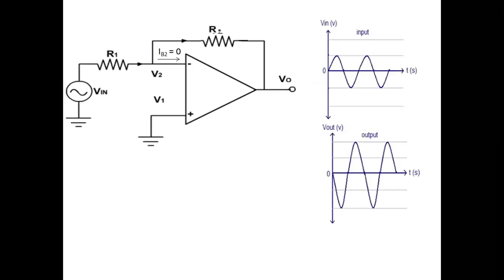So here we are supposed to study about the inverting amplifier. If we are taking the IC 741, we are saying this is the inverting terminal, this is the positive. At that time, we are supposed to give input. Where will we give it? We will connect that input to the inverting terminal, because here we need the output that will be inverted with respect to the input. So we will get the output from this side. So we can say VO.